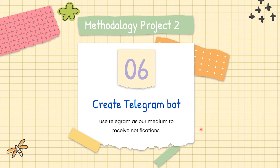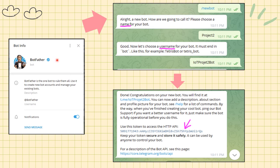So step 6 is we will create a Telegram bot. We will use Telegram as our medium to receive notification from the Favoriot IoT platform. In the first picture here you can see, firstly we find BotFather in Telegram. You can search by its username, which is BotFather, and then we follow all the instructions.